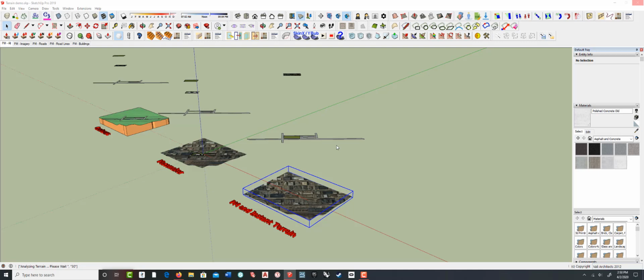You can draw cubes or circles or any kind of geometric primitives and place them together in SketchUp, and you can select all of them and make them a group, and it will just drape a landform over top of it. And then once you get that basic landform, you can use the Artisan tools to smooth it out, manipulate it, and modify it. So it's really a fantastic way to do quick landform studies without having to worry about thinking about contours. You're just really sculpting digital clay that way.